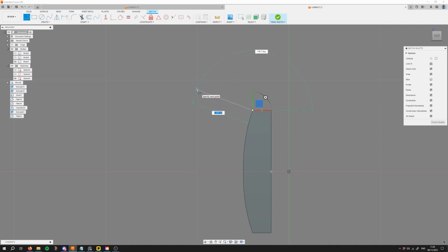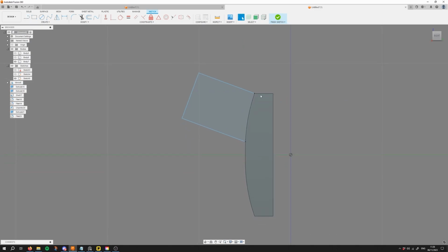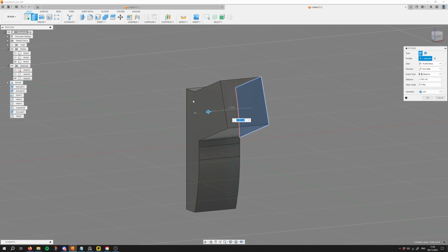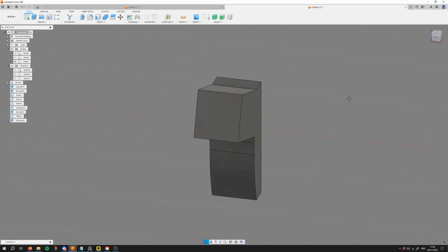Let's try to create a little sideways. Make sure it's the right angle, like so, and close the sketch. You don't have to close your sketch fully. You don't have to connect these two dots when it turns blue. That means this edge here is already part of the sketch basically. So what's left is finish your sketch, press E to extrude, and then as we learned, snap to the face right here. You want it to join together, press OK.